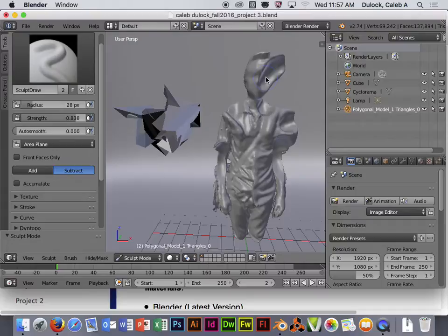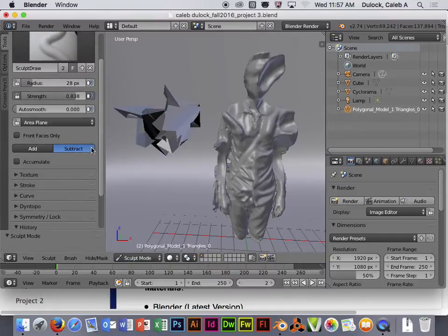Now again, I've been doing all this editing on top of my character model. If you've been trying to edit on top of a cube, the cube may not be doing a whole lot for you, and that's because the cube doesn't have a lot of polygons on the structure. You may have to subdivide it in edit mode a couple times to give yourself some things to work with. But if you don't, that's okay. There's a cool option we can change inside of the Sculpt tool in order for it to break up the surface of a polygon automatically to get the effect.